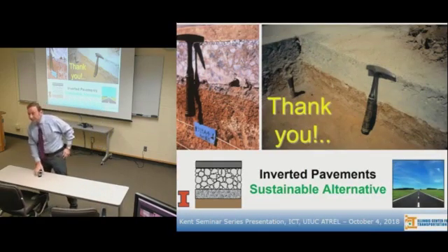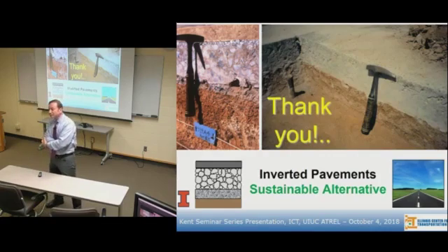So I think it was when you introduced that South African section that talked about a surface treatment of 12 to 50 millimeters. That 12 millimeters is probably not an HMA, right? You had said something about a chip and seal type thing. I just couldn't see practically how you could put down half an inch.